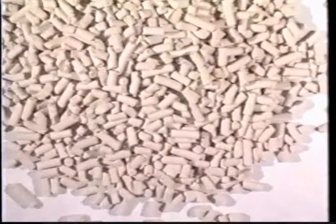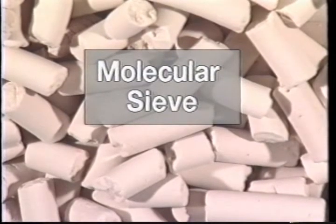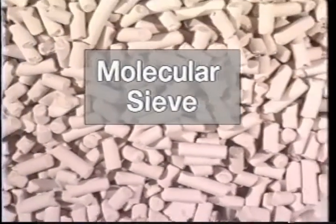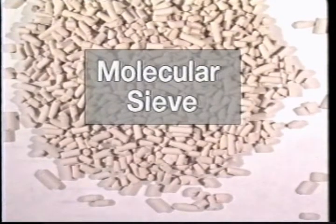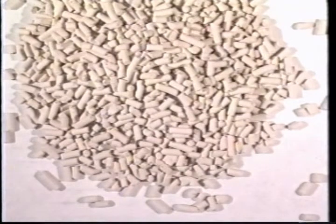Molecular sieve, used in the pellet form, will suppress dew point by 60 to 80 degrees Fahrenheit. A coalescer must be used to remove oil from the air because the molecules in compressor lubricating oil are larger than the pore size of the molecular sieve. Without a coalescer, oil droplets will collect on the surface of the molecular sieve, blocking water absorption. This is also common to activated alumina, frequently used in twin tower regenerative dryers. The coalescer in Filenco dryer filters and twin tower regenerative dryers is critical for long life of the desiccant.